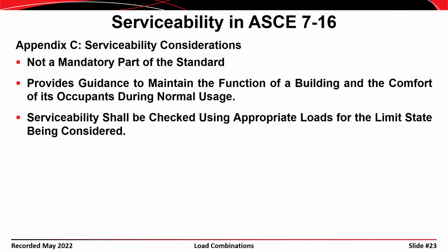It says that serviceability shall be checked using appropriate loads for the limit state being considered. But it doesn't go on and give you any idea of what the loads should be. So there's a lot of latitude left here to the engineer of record in deciding what constitutes appropriate serviceability and what loads the serviceability limits should be checked at.